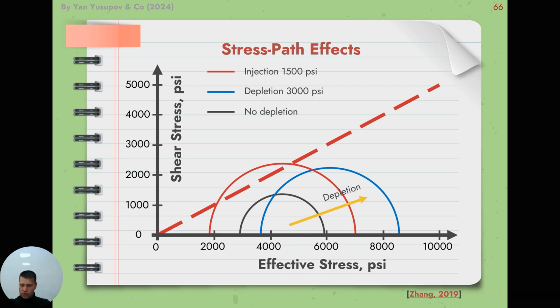This figure is a Mohr-Coulomb circle illustrating the mechanism of shear failure induced by repressurization. The rapid pore pressure increase doesn't diffuse significantly into the matrix, and the injection doesn't change the total stresses, but simply reduces the effective stresses, moving the Mohr circle to the left.